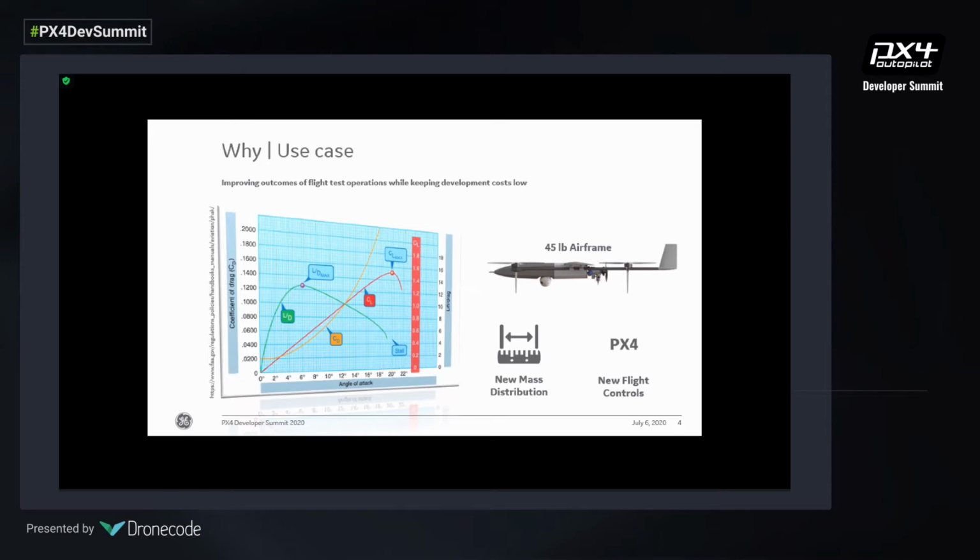So we want to identify any of those really exciting components of the airframe characteristics prior to actually going and flying the vehicle. And so in that process, the first step that we took was to conduct basically the paper napkin exercise of doing an assessment of the vehicle. And we determined that this particular vehicle, with the initial configuration that we had identified, had a static margin that was smaller than we would have expected.